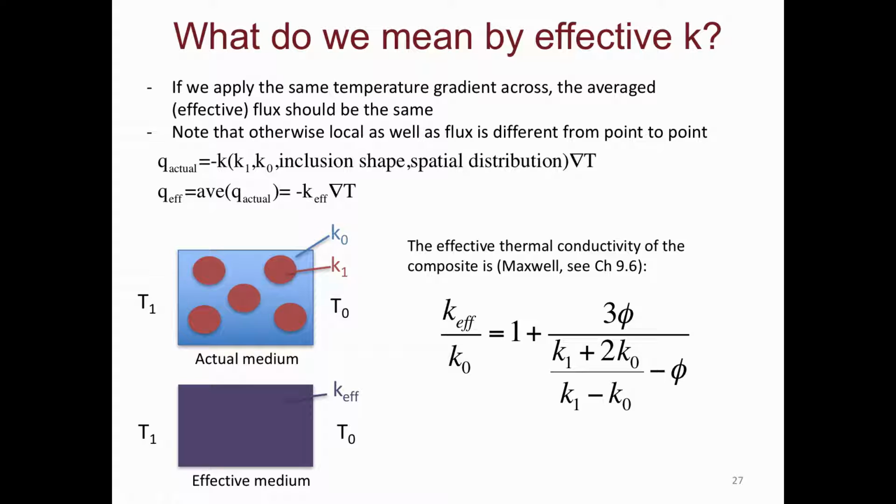So when I think in series versus parallel, that's where you could actually have this case of, let's say that you have layers. Right? So if you're transporting parallel to the layers, okay, they're all acting in parallel. Whereas if you're going in the cross direction, they're in series because essentially, the one that is the throat or the bottleneck will end up being the dominant one when they all have to go through each other to go across.